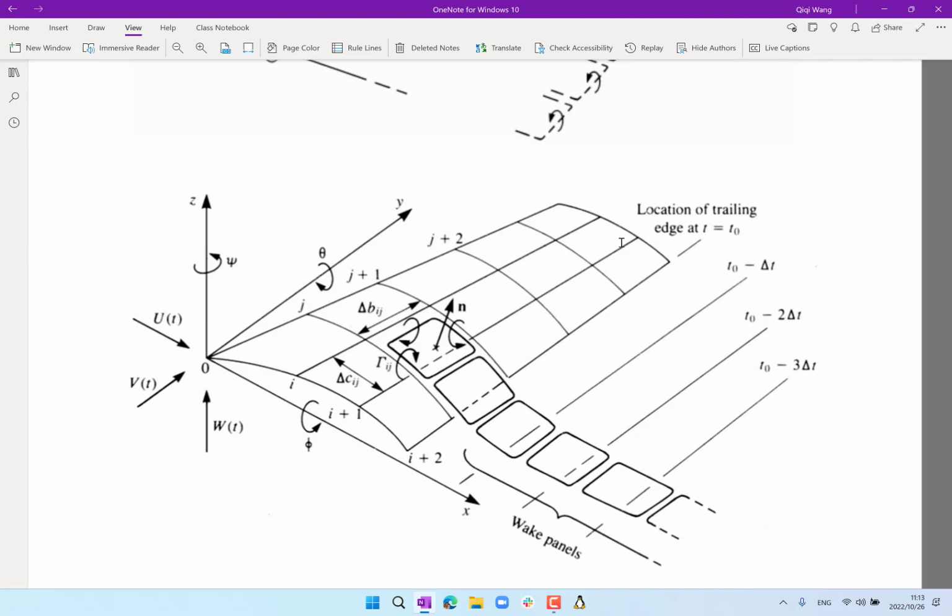So literally, we are approximating the air downstream of an airplane as if the airplane wing is a device that continuously shoots vortex rings in the downward direction, right? So this vortex ring, as we have seen from the equation obeyed by vorticity, is going to go with the flow.